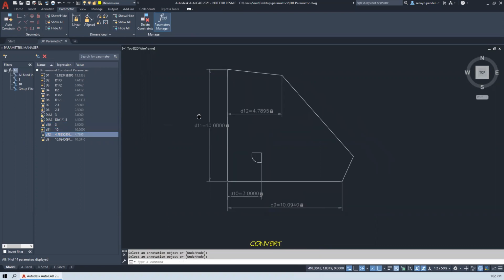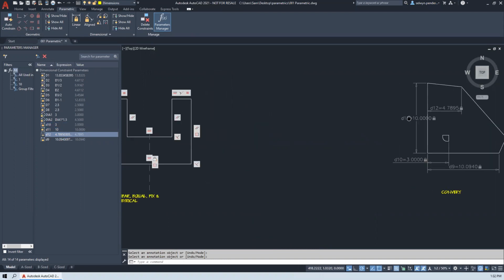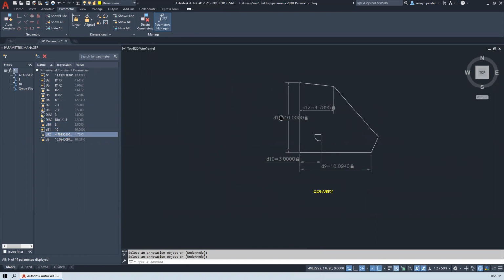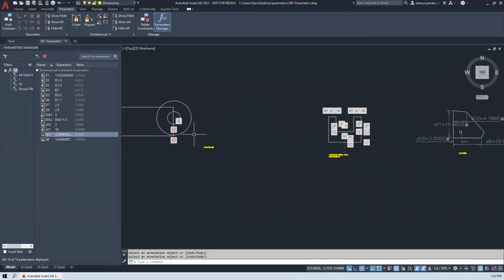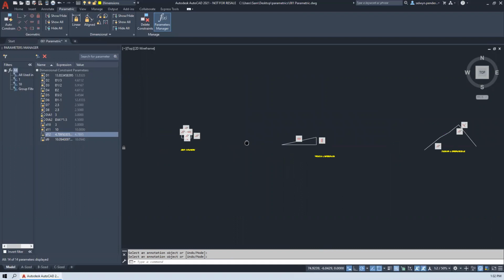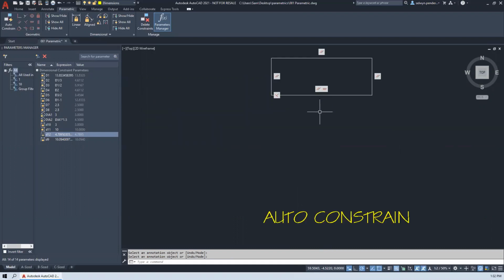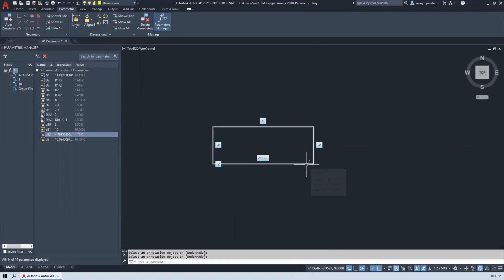You'll find parameters, be it dimensional parameters or geometric parameters, do not print. There is a way of getting them to print, and we'll go through that a little bit later. However, we'll go back to our rectangle and we'll look at relieving or removing constraints.